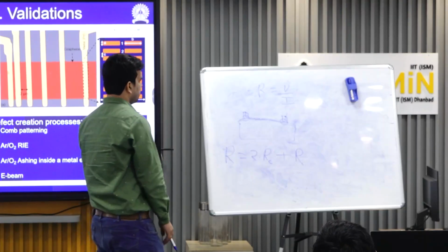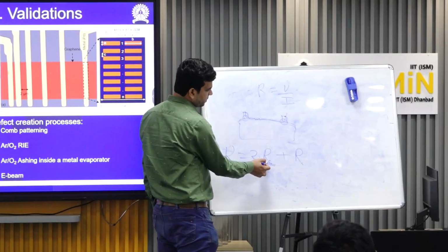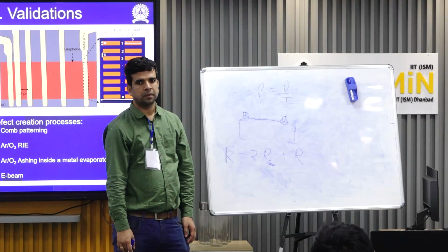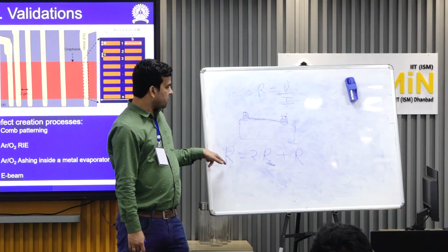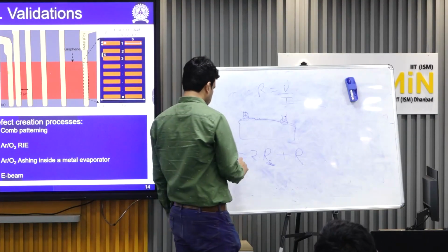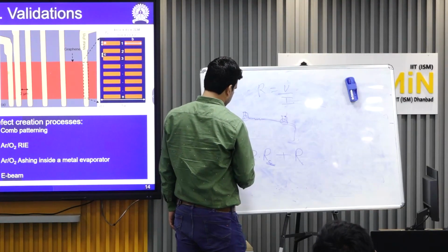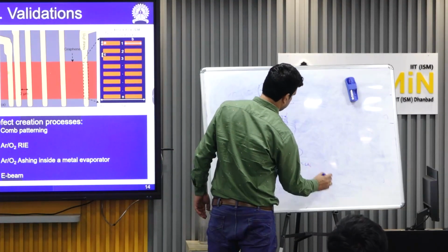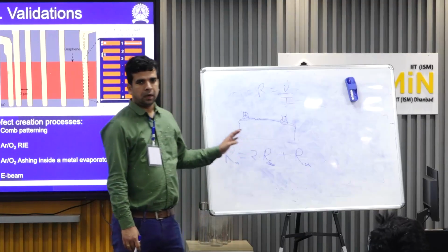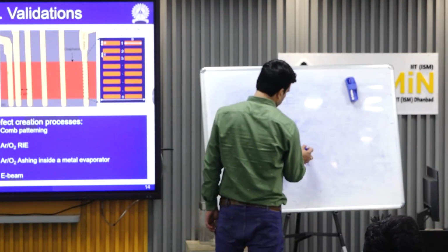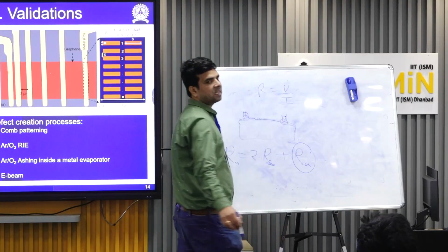Now our goal is to find out the contact resistance. This R we can calculate by V by I, which we know. So this R is known. I am calling it R measured, and this is R channel. Understood this? Now the beauty is that we know the formula for the channel R.